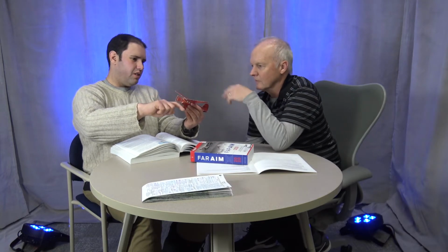Right, so the air that gets pushed down on the left side at the nose will come around underneath the fuselage in a spiral, and it'll hit the right side of the tail. Well, when it does that, if it hits the right side of the tail, that pushes the tail to the left. That pushes the plane more to the right.